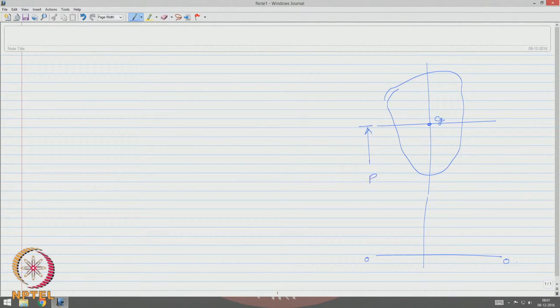So, the centroidal axis is located at distance r, whereas the beam is subjected to a bending moment of this nature, which causes tension in the extrados and compression in the intrados on extreme fibers, the applied moment being M. Therefore, this makes the neutral axis shift to the bottom, that is, towards the center of curvature.